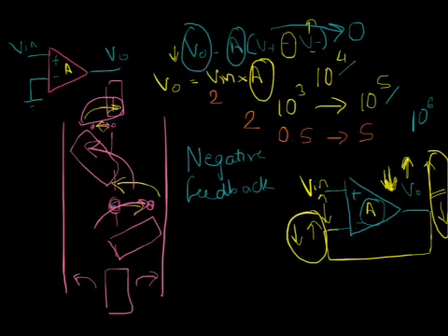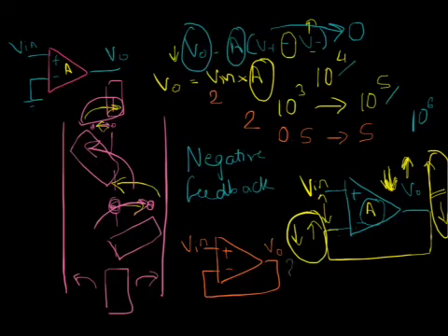So this circuit that we have here, where we basically connected the output to the negative input, and we gave an input voltage at the positive terminal. Let's try to find out what exactly is this value going to be. We know that since we've assumed A to be infinity and Vout to be a constant, the two terminal voltages have to be equal.